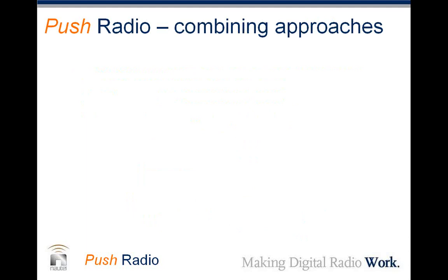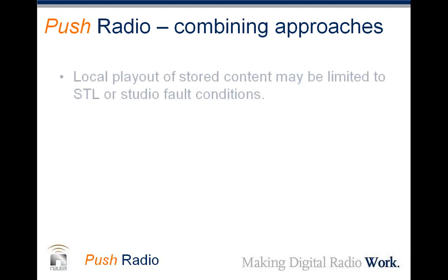Let's talk about how this could work in a conventional station. We can combine the traditional approach with the push radio approach. For instance, local playout of stored content can be limited to STL or studio fault conditions. If your STL dies, or the power goes off in your studios, you can let the transmitter automatically pick up the ball, start playing off a playlist, and you have a backup even when your studio is dark.